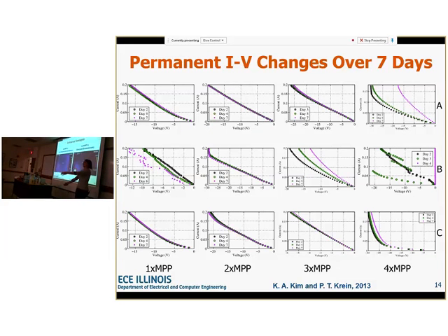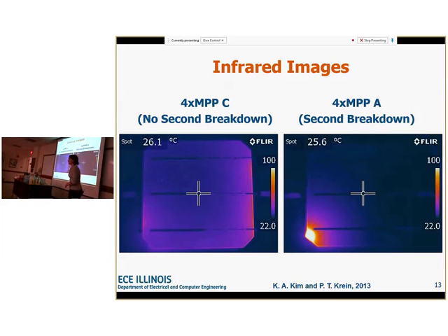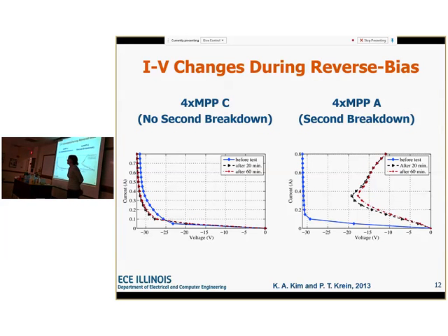Oh, yes. So go back to slide 12. Yes. So you're not showing what's happening in the generating power part. But based on what you said before, if nothing is changing, wouldn't it be better now? Because if it's hot spotting later, wouldn't it be drawing less power because now the IV curve is shifted? So if you're drawing the same current, there's less voltage.